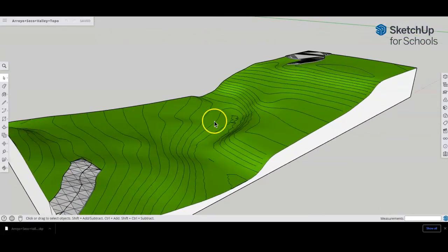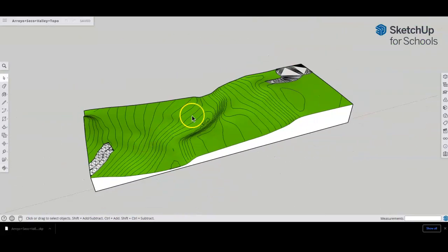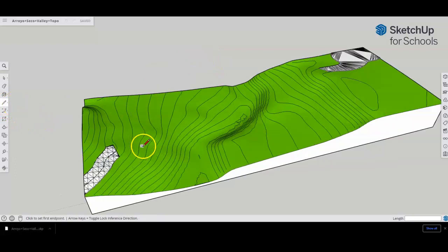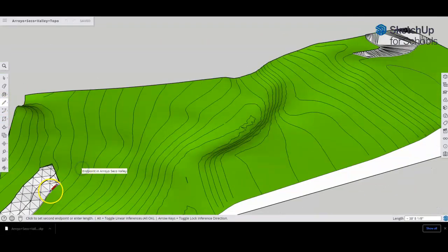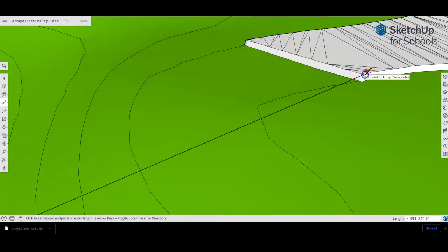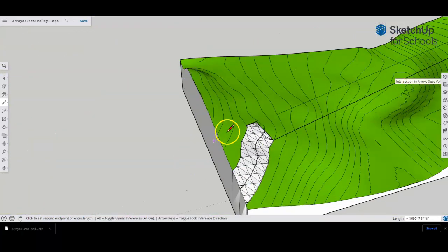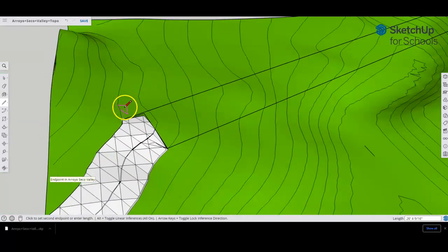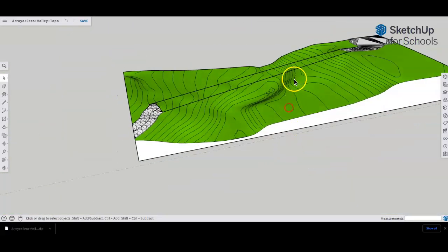we're going to go ahead and get a measurement of the distance from this street to this street. So we're going to draw a line, the letter L for line, or the line command right here. I'm going to grab this corner here and this corner here. I'm going to do the same over here. So I'll hit the letter L again. Zoom out. Zoom in over here, and let me grab this one right here. And there we go.